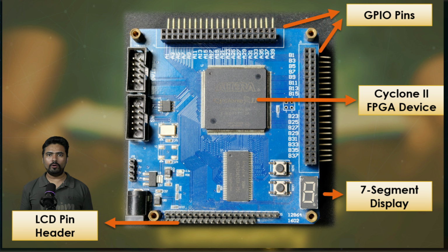I will also give you a basic understanding of how to use the Quartus IP catalog. This catalog contains pre-designed VHDL components that you can select, drag and drop into your VHDL project. This feature simplifies the designer's life because most of the work has already been done in these catalogs. All you need to do is learn how to generate these IP designs and then incorporate them into your own projects. I will provide an example to show you how to use the Quartus IP catalog in this learning series.